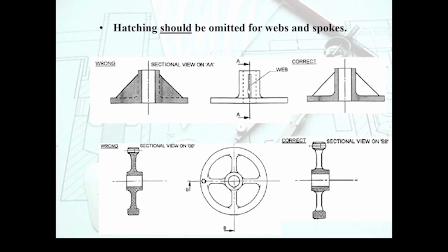try and avoid sectioning standard parts. If there is nothing to show on the inside, a very common scenario is a web or a rib, which is basically just a bit of material to stop the collapse of these two features and apply some stiffness without adding loads of material.